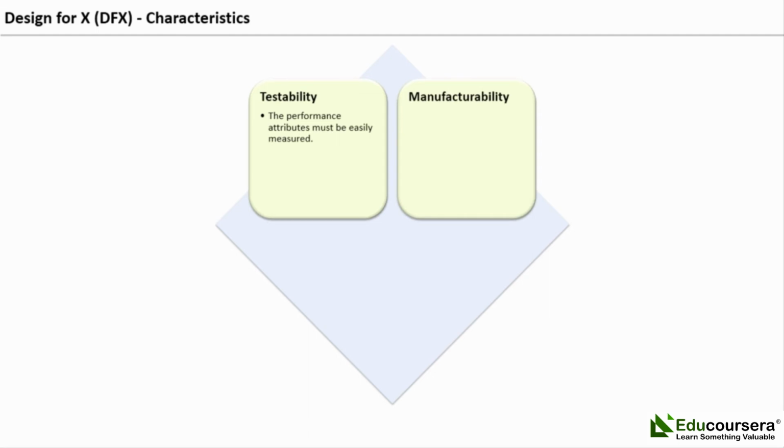Manufacturability. The concept of design for manufacturability, DFM, includes the ability to test and ship a product. Producibility and manufacturability are terms used since the 1960s. Design for manufacturability, DFM, has been the dominant term used since 1985. A design must simplify the manufacture of a product through a reduced number of parts and a reduced number of manufacturing operations.